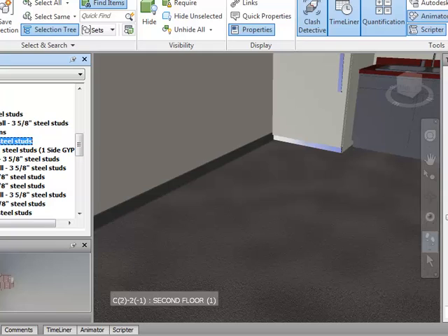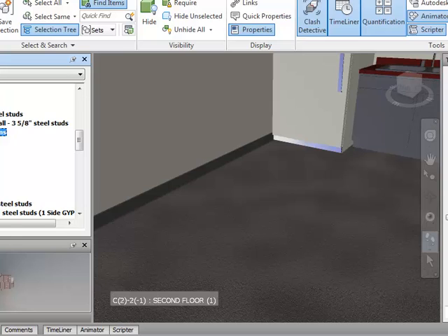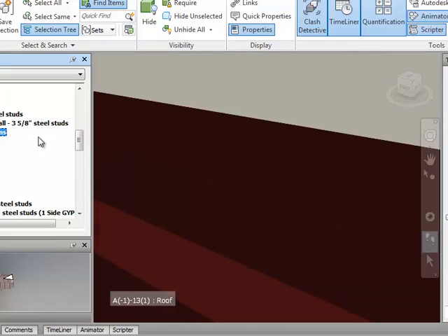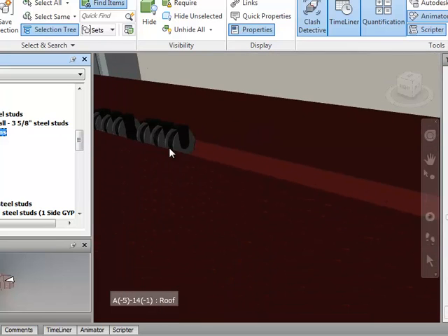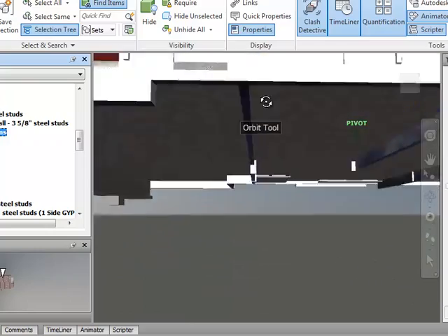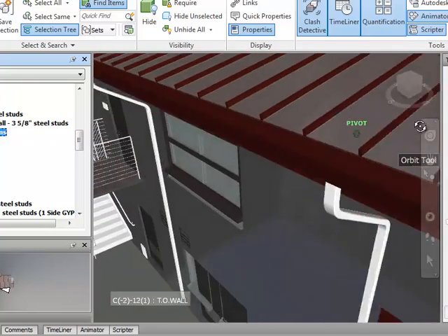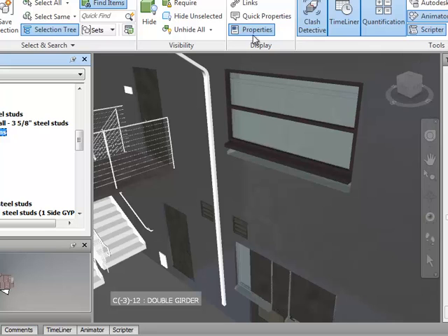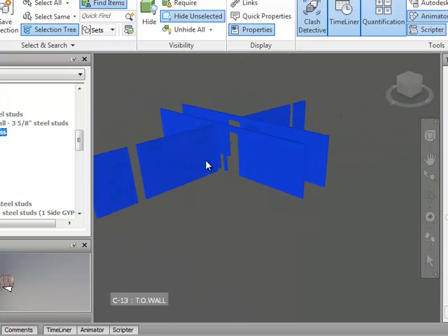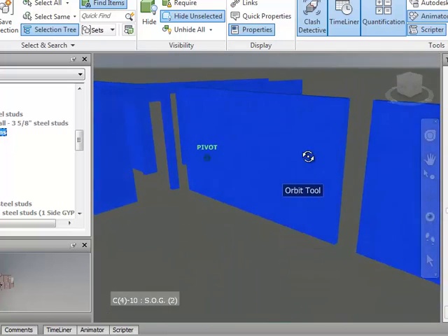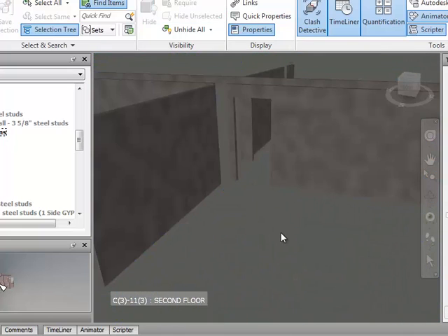Correct. Yep, the STC ones, those are steel stud, demountable. That's probably the toilet partitions, I think. Or it could be, I'd have to look at it. No, I think the toilet partitions were in special equipment. So demountable partitions, like office cubicles sometimes, are kind of like movable walls. Those would be a specialty item, so it's likely Division 10, possibly Division 11.